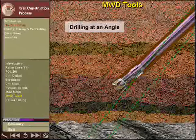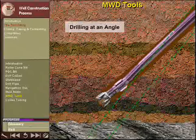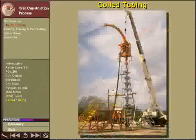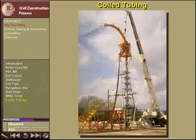To steer the hole during kickoffs or course corrections, the system is oriented using MWD readings, so the bit will drill in the direction of the navigation sub's offset angle. Slight deviations from the desired angle can be detected and corrected with minor oriented drilling intervals before they become major problems.